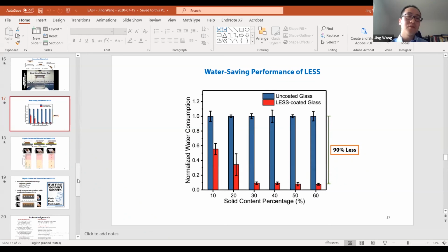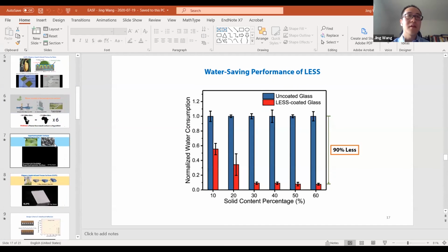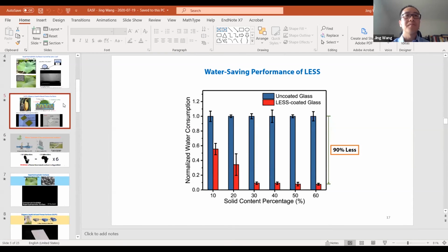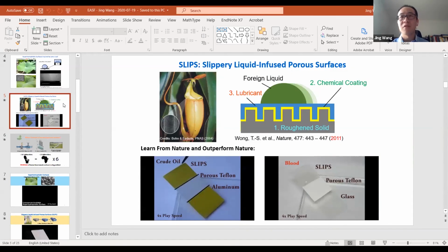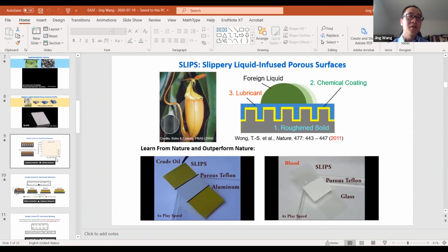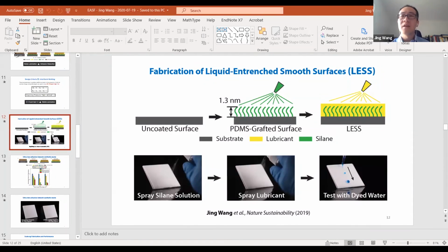Yes. So this is a good point. For slippery systems, they have already been demonstrated a lot by other groups, using slippery surfaces to prevent marine fouling or underwater fouling with algae, barnacles, and mussels as well. I think we have some advantages and disadvantages compared to slippery technology. First, the advantage is we may have an even lower adhesion to barnacles and mussels because we have a smooth underlying surface.